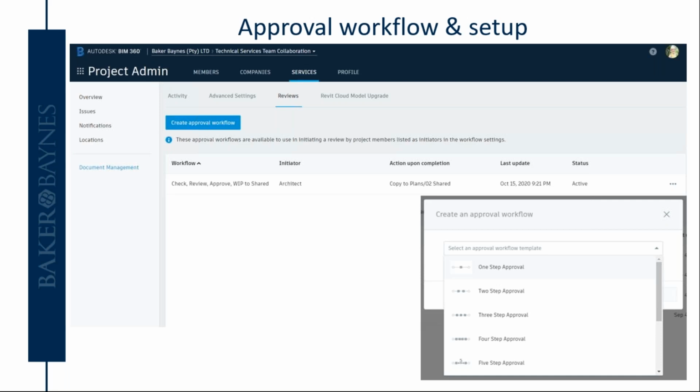So, for example, if a contractor needed to make a few cores at various locations after concrete has been cast, he could then mark out the core locations and then send it to the architect and the affected engineers for approval. Then once all the consultants are happy, they will then approve this, and the review will be closed, and then the contractor can proceed with the coring.